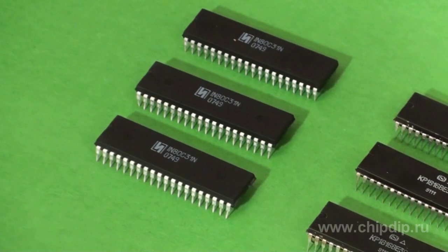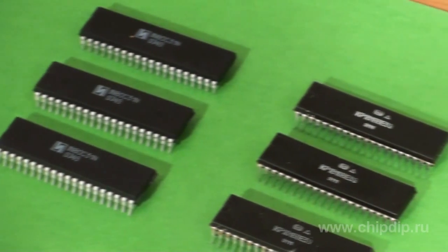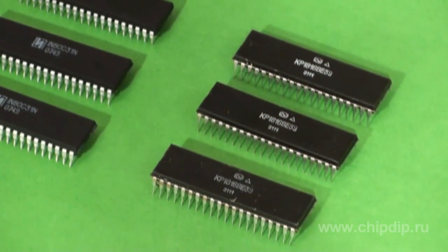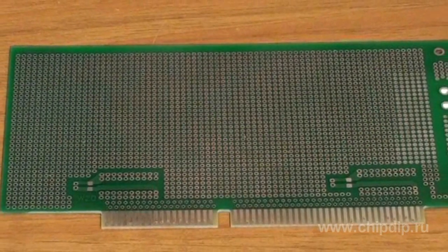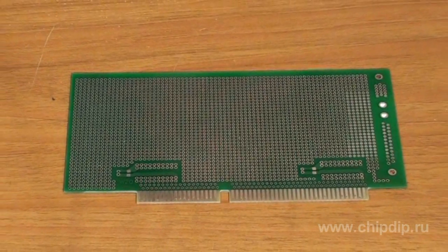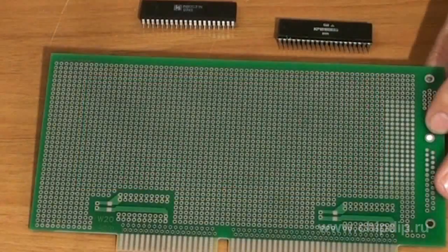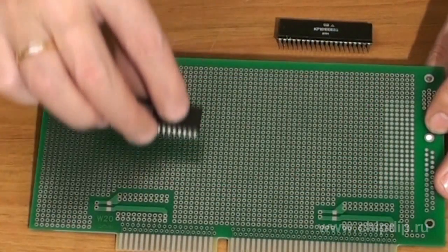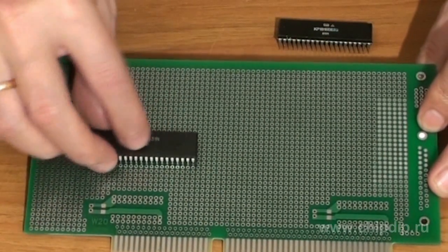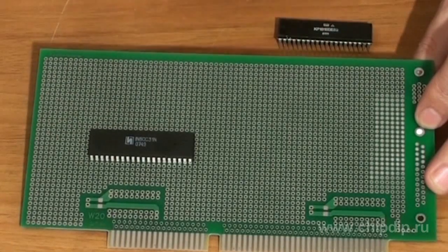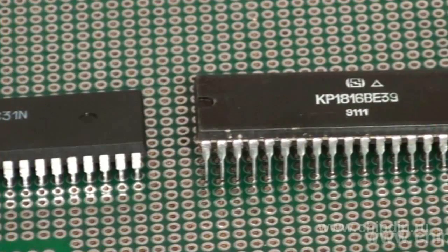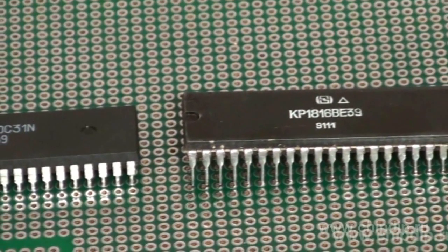For microchips with many leads, like in DIP 40 housing, where the spacing difference between the leads is up to 0.8 mm, the wiring may be troublesome. For example, the breadboard DIP ISA is intended for wiring imported chips in DIP housing. For this reason, microchip KR1830VE31, designated as IN80C31AN, can be easily mounted on this board, but the leads of chip KR1860VE39 do not coincide with the holes.